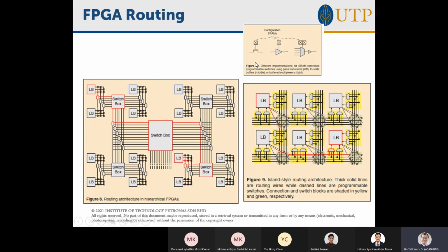All right. So this is the FPGA routing, and again, you don't need to do any of this. The tool does this all automatically for you. I just repeat, you are just writing Verilog RTL, and you're just saying at the end of the chip, this pin goes to what logic, and then the tool will figure out, okay, I'm going to use this logic block, I'm going to connect it by this line here going through it like that, and then I'm going to connect to the output by going like this line here, going this path here and all that. The tool does that automatically for you. But this is how an FPGA works.